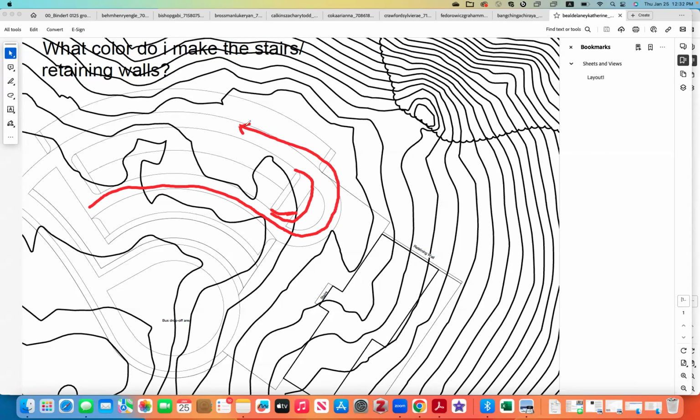If I need to drop people off, then I drop people off on the far side of this road. I pull a little bit closer to the curb and then drop people off, and then I flow back, merging back into the parking lot. So turning 90 degrees to loop around is, I would say, a secondary choice other than pulling around and dropping people off. So I would move the island back and simply enlarge this area to the curb and to the drop off area. Does that make sense?